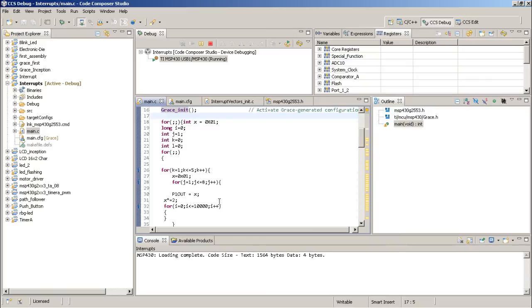So normally it will be showing those patterns, but whenever it gets an interrupt, it will stop the execution of that program, complete the instruction that is being executed, and go to the ISR. Context saving will take place, context switching will take place, ISR execution will take place, then it will resume back to the main program. So that is the working of this main program.